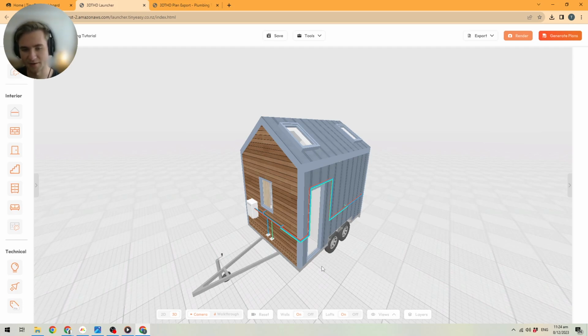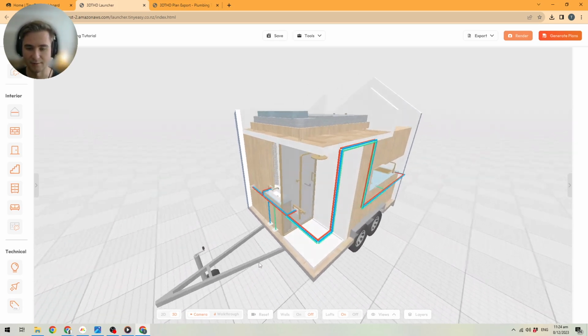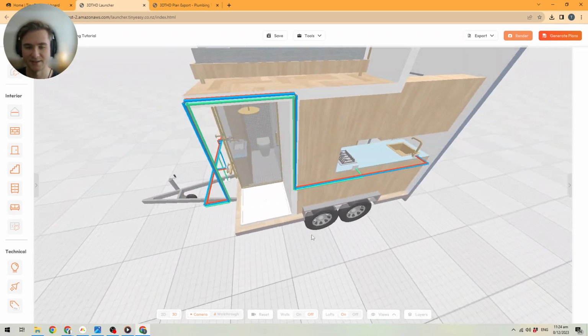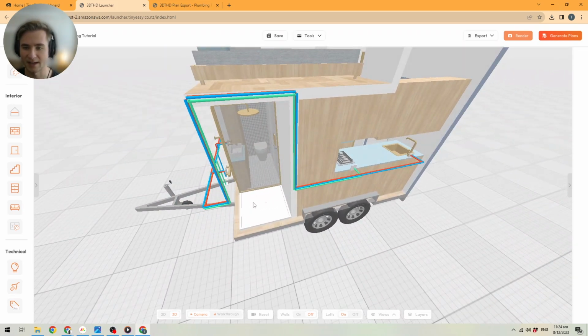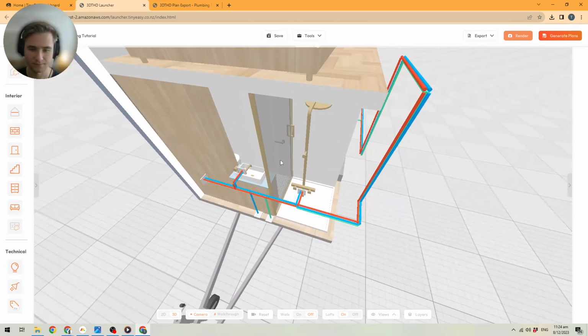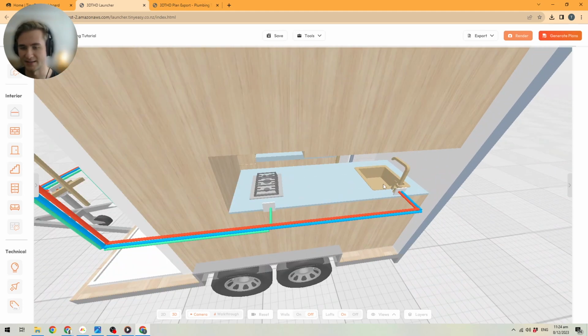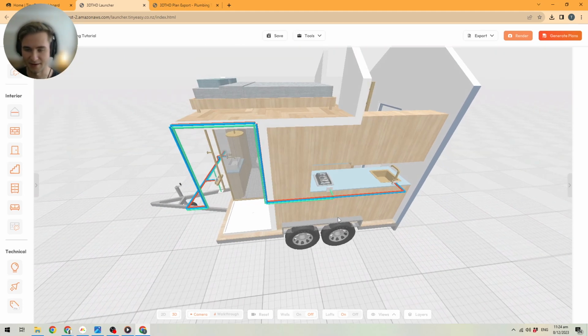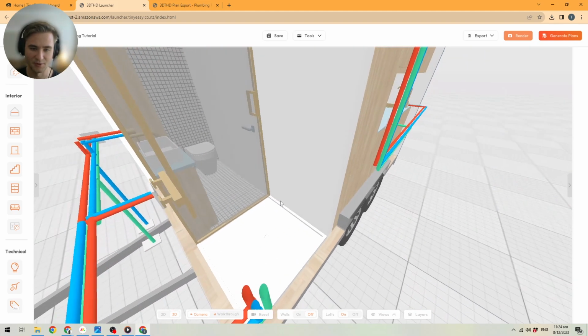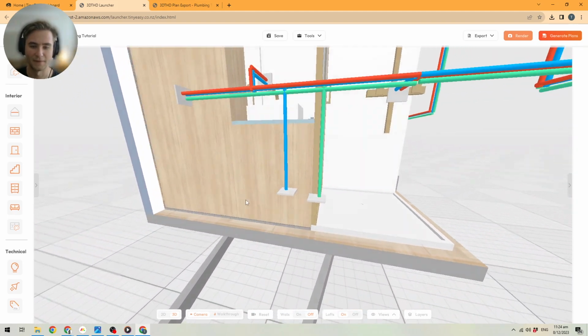One more thing that I wanted to talk about, of course, once you've created your hot, cold, and gas connections, is that you probably want to create your wastewater connections as well. So what I'll do here is disable my walls one more time, and I will think about what my wastewater system is and how it will work. We actually have 3 points that will have wastewater, and that will be my vanity right here, my shower, and my sink. And if you think about it, where does the wastewater start? Well, usually under the outlet of the object.